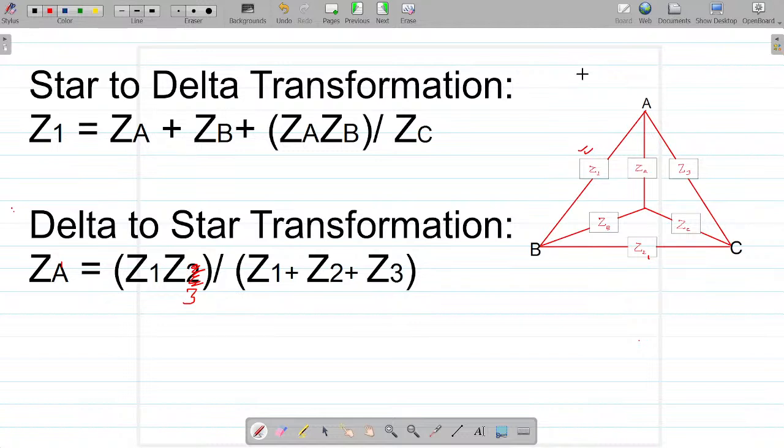In general, when you are converting a star network to an equivalent delta with identical elements, the star to delta conversion of a star network with identical elements increases the impedance by 3 times in the corresponding delta connection and vice versa. I'll tell you how.